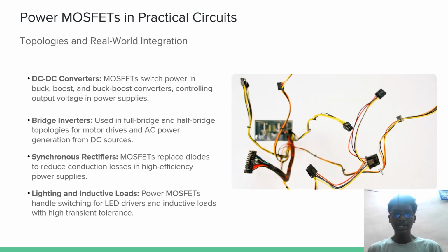MOSFETs in practical circuits: topology and real-world integration. DC to DC converters, bridge inverters, synchronous rectifiers, lighting and inductive loads. DC to DC converters: MOSFETs switch power in buck, boost and buck-boost converters, controlling output voltage in power supplies.